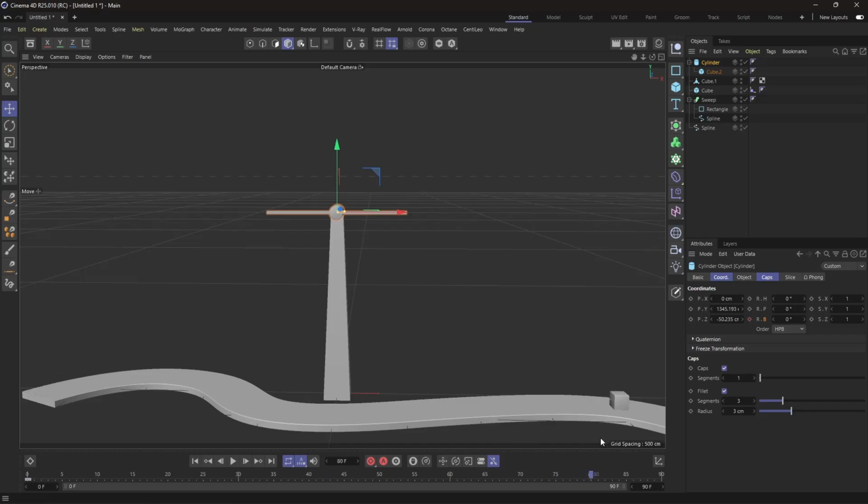And then at the end, because I want this animation to loop, I can make it 360, but 360 degrees is the same as 0 degrees. When you calculate it mathematically, 360 degrees is the same as 0 degrees, and at the start we have 0 degrees. So at the end, instead of putting 360, I'll make it 359 degrees and set another keyframe. If I put 360 here, we have a double step of position, because 0 is the same as 360. But if I have 359 here, the next frame will be 360, which is the same as 0. So this way we'll have a perfect looping system.